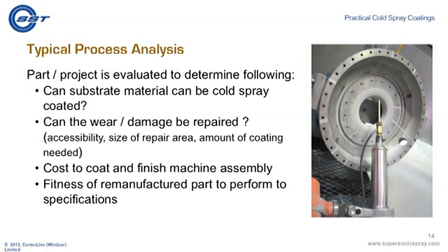We're going to carefully examine your component and determine the following. Can the substrate material be cold sprayed at all? So long as the material has enough integrity to accommodate the high velocity metal particles, in most cases the surface will be cold sprayable. And these include metals, glass, and ceramics.